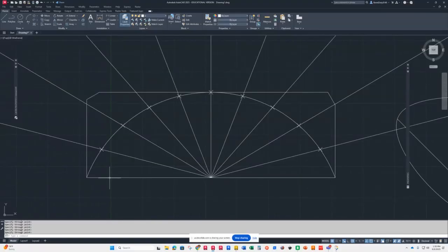Now there was a measure command on here, but honestly, if you want to measure something, not put dimensions on, but let's say you want to check a measurement, and you try to use the dimension command, depending on the size of your geometry, like if it's metric, you're not going to see it because of the scale.